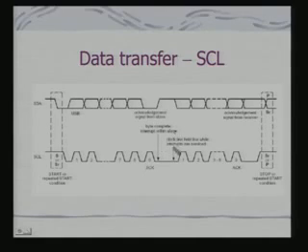After this, what happens? The slave will pull down the clock, because the slave would like to now have a wait state, because it may be using an interrupt call to transfer the data or do any other housekeeping task. So, it introduces a wait state here. When there is a wait state, effectively no data is sent. Again, the clock starts pulsing at this point, and from this point onwards the data transmission can start.